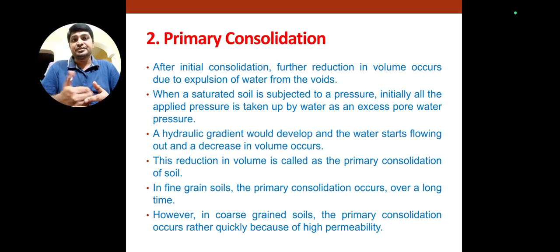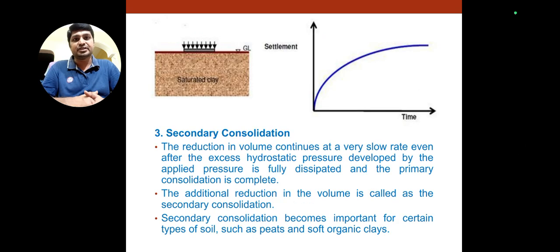In fine grained soil, primary consolidation occurs over a long time. However, in coarse grained soil, it occurs in a very short period. That is the difference between fine grained and coarse grained soil. When we observe the diagram, we are observing a saturated clay mass.